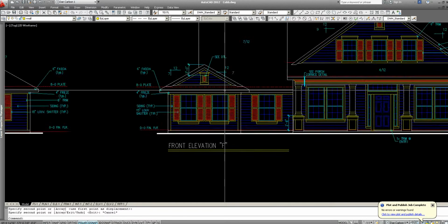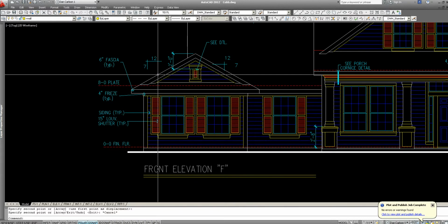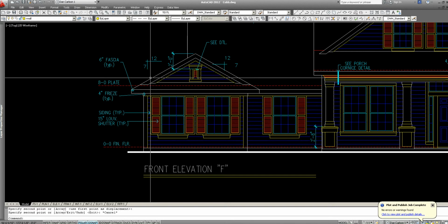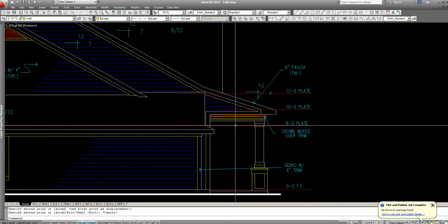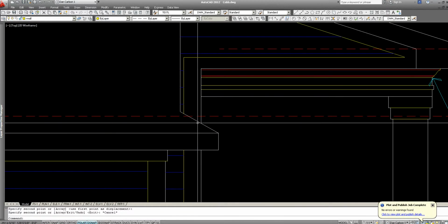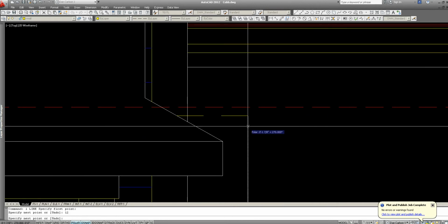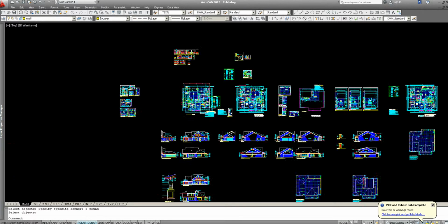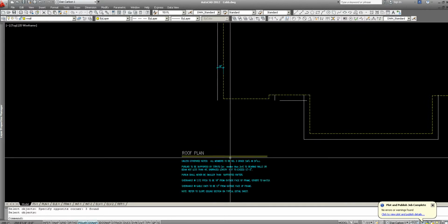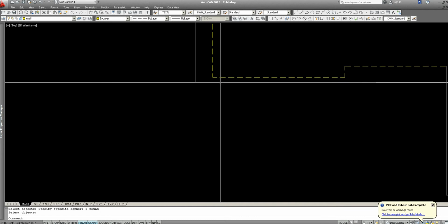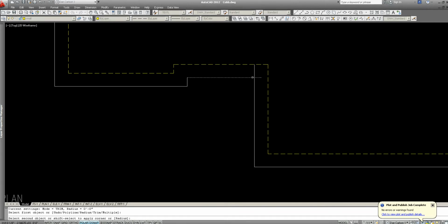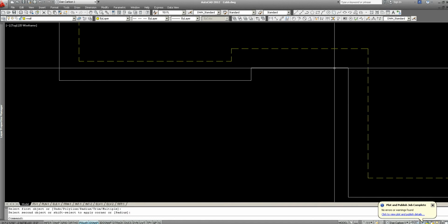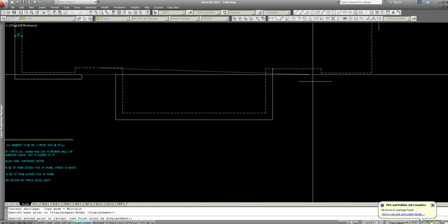And then we have this roof here, which is actually a full hip on all three sides with a gable sticking out of it. So looks like we have a 7/12 there. And I gotta find that side of the house. Where's that side? Here it is. It doesn't say but I'm guessing this is also a 7/12. Close. Yes, so that was also a 7. So if we have a 7/12 on this side and a 7/12 on this side, then that means that the overhang is also going to be 18. So 18, 18, 18, 18. Just come right around this corner. For now, we're just going to fillet all of these corners, even though they may not be that way on the final pass.